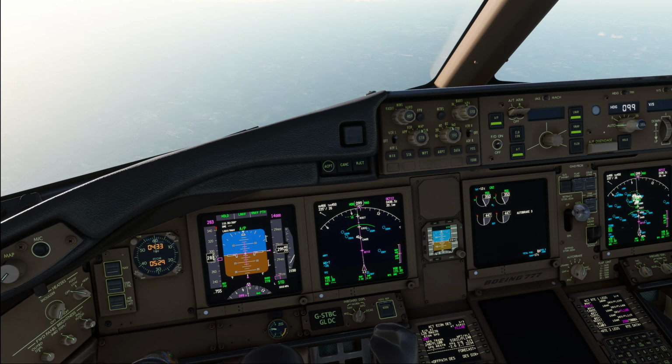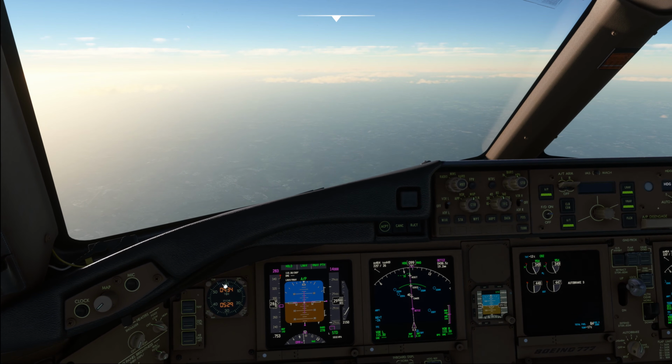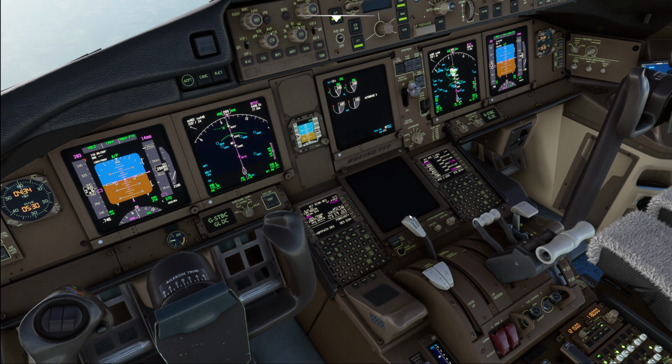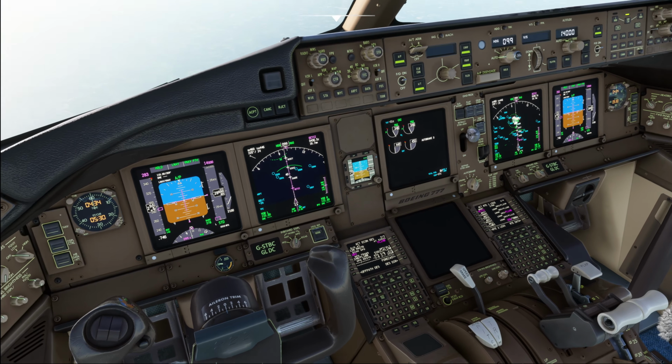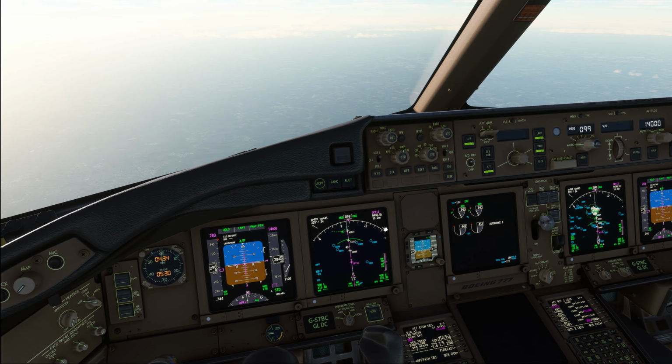However, many long-haul pilots just don't bother with that kind of optimization anymore, because we have to face it, you just flew a night flight, you're probably tired, and if you then start to play with your speeds and increase the speed, yes, all that good stuff works perfectly fine on short haul, and it would work on a 777 as well, but many long-haul pilots would simply use the speed brake while maintaining the present speed in order to catch the path again. The 777 has a very, very efficient speed brake.